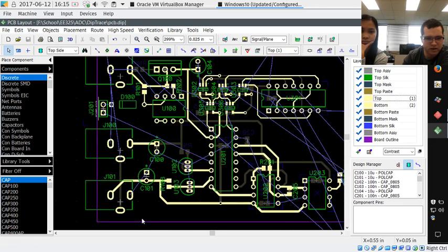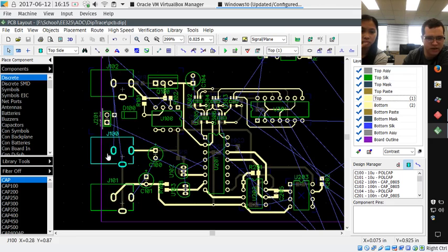So what we've got here is analog input power jacks, and the digital power jack. The protection circuit is here, with an IRF510, which is just a standard power transistor. We also have these 5 gates, which are part of the priority encoder, and this chip contains the rest of it, the NOR gates. This is our switch IC, the DG409DJ,